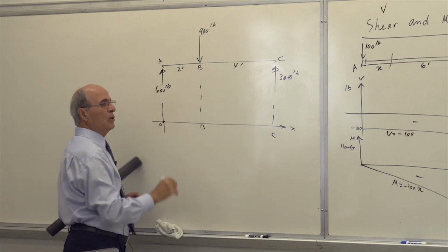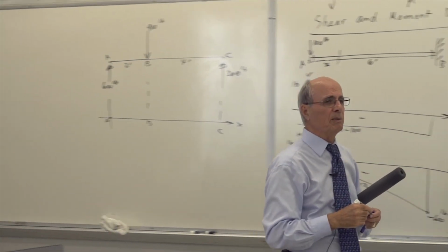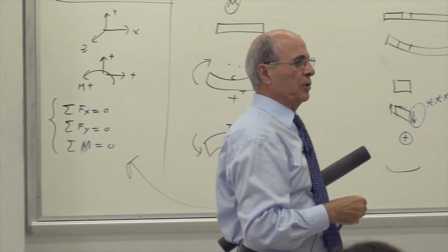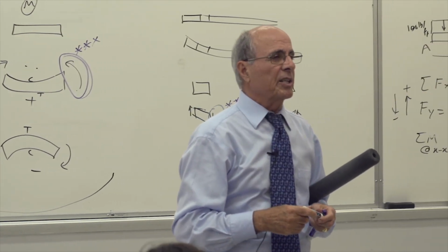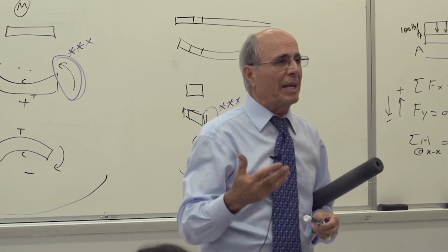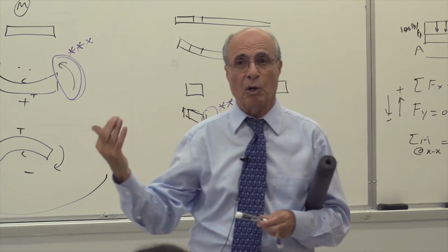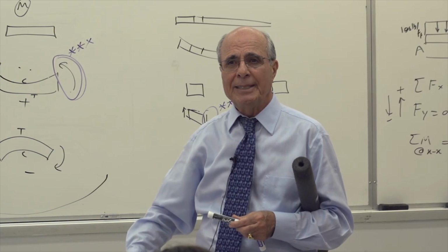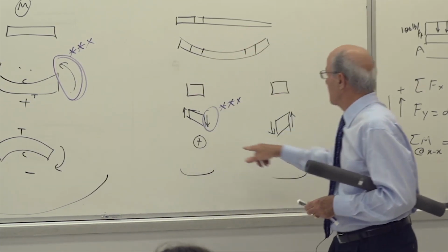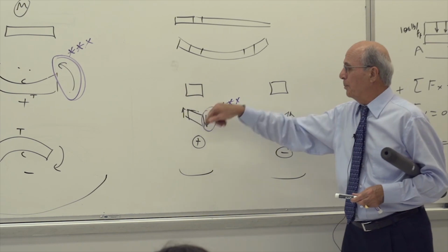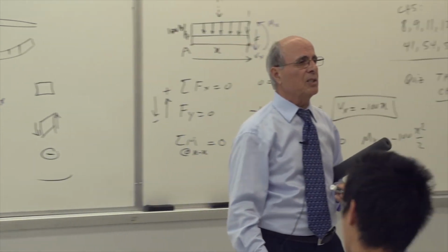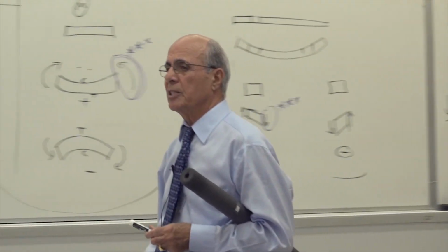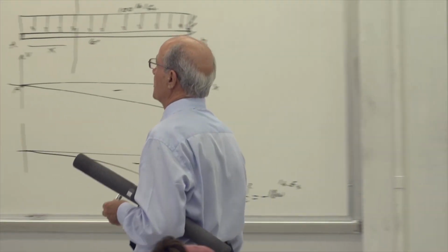Now, what's the shear value at A? You have to be a little bit quicker. What's the shear value at A, an epsilon after A, in other words? 600, correct or not? Is it plus or minus? Everybody should have an answer there. If you have not answered, then you are not looking at the sign convention correctly. The force is up, shear is down. Which one is it? It is plus. So I must start with plus 600. Yes or no? It's the reverse of that one, guys.